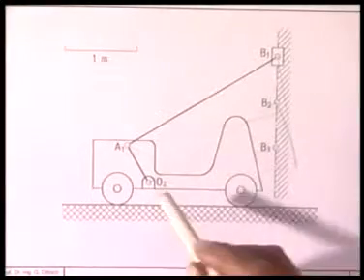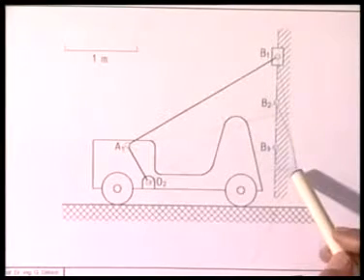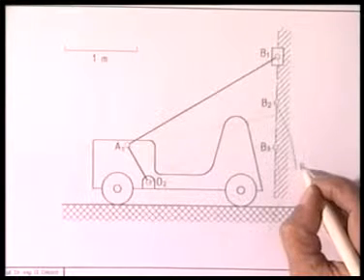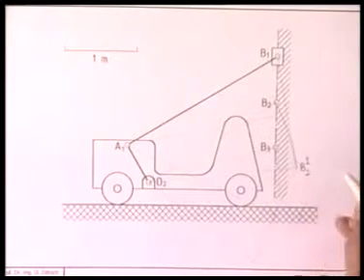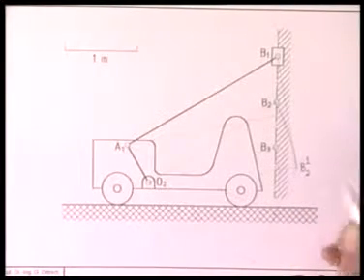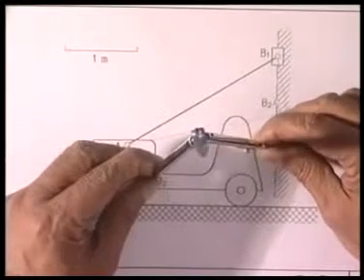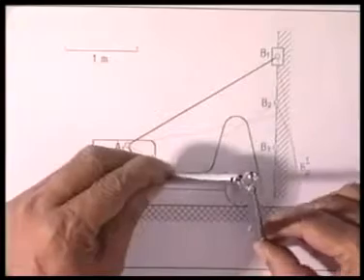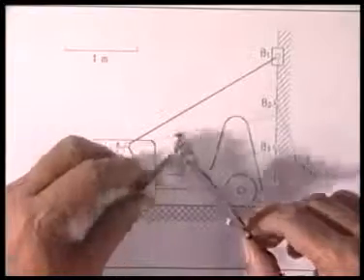So we rotate B2 with O2 as center. This line O2B2 is rotated by 26 degree, and this point we call B2 inverted on the first position, or B21. Because we are holding the first position fixed, the inverted position of B3 I can get by rotating O2B3 by 52 degree.